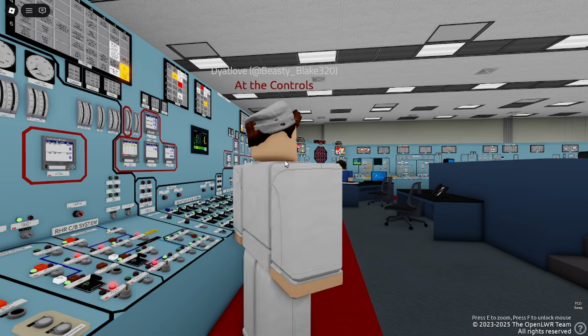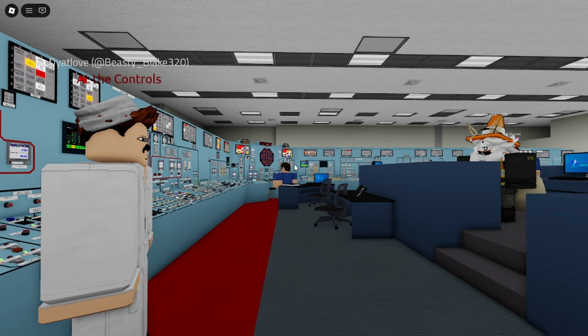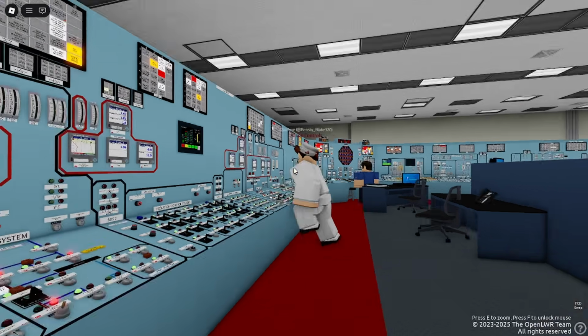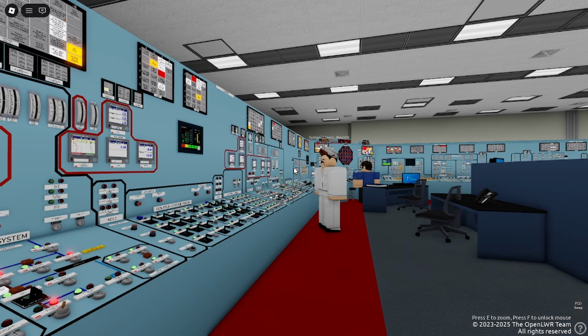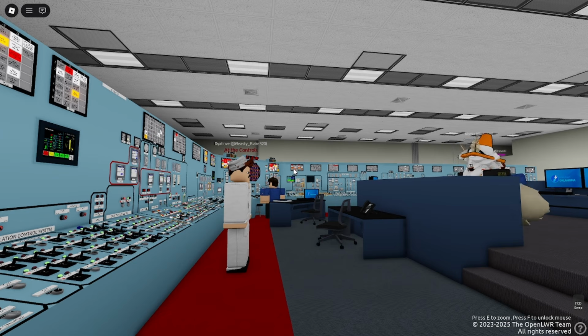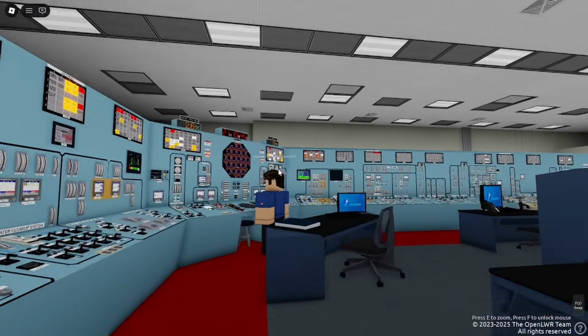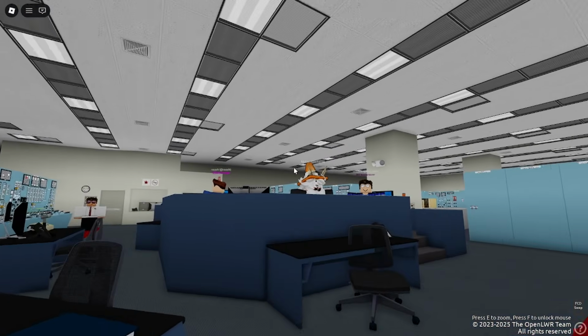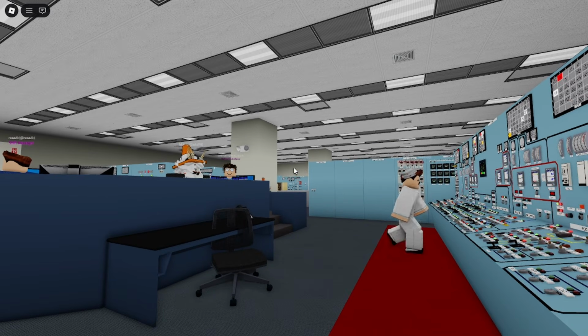Dyatlov, is any system that takes suction from SP currently injecting into the RPV? Stand by. Standing by. And there's currently no suction from suppression pool for RPV. Understand there's currently no suction from suppression pool. That's correct. Right, crew update. We're entering PPM 521 primary containment control on low suppression pool level. End of update.